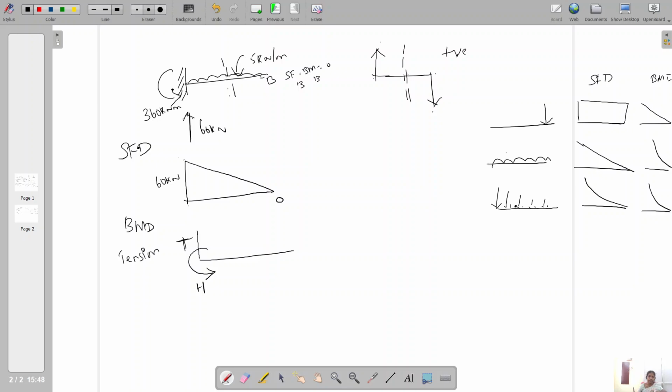So you mark this bending moment, a parabolic curve of 360, also in negative. It is a parabola curve, negative in magnitude. Okay, I think you should be able to analyze the support characteristics, whether it has a horizontal reaction, a vertical reaction or a moment, and where the bending moment is 0. This should all be well known to you before starting the structural analysis subject.